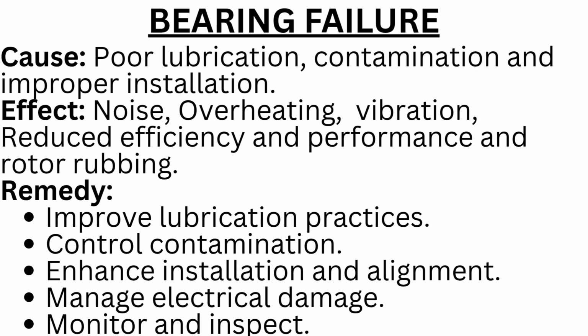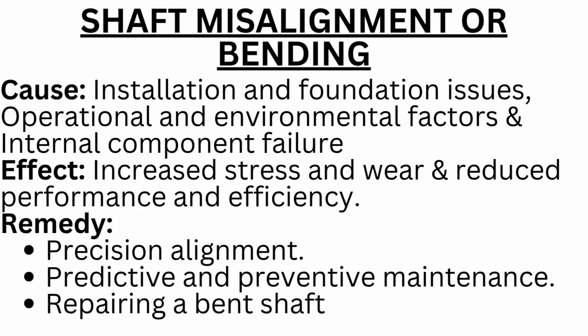The first mechanical failure that we will look at is the bearing failure. Cause: poor lubrication, contamination and improper installation. Effect: noise, overheating, vibration, reduced efficiency and performance and rotor rubbing. Remedy: improve lubrication practices. Control contamination. Enhance installation and alignment. Manage electrical damage. Monitor and inspect.